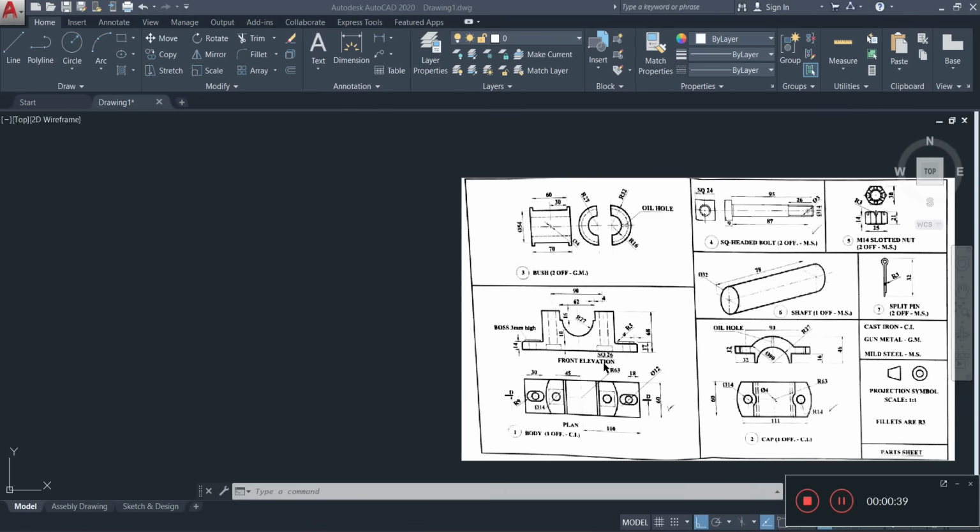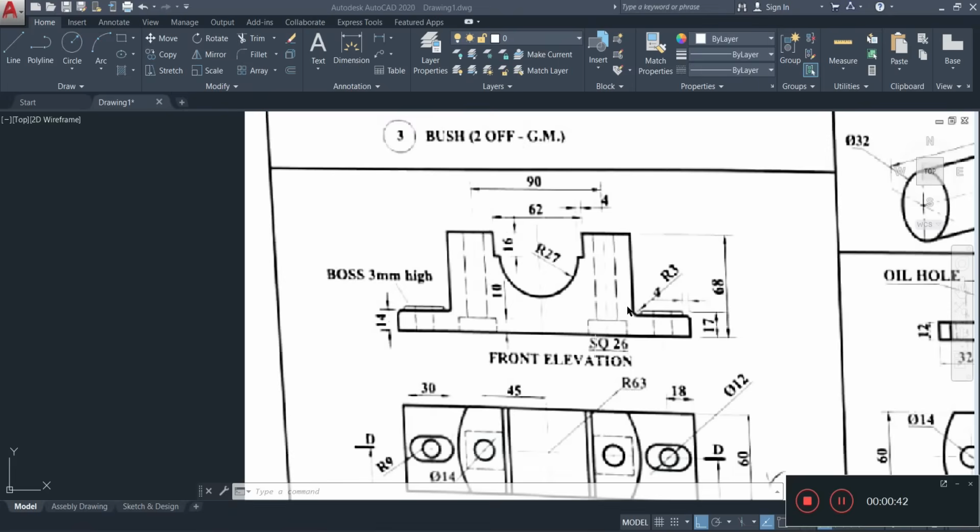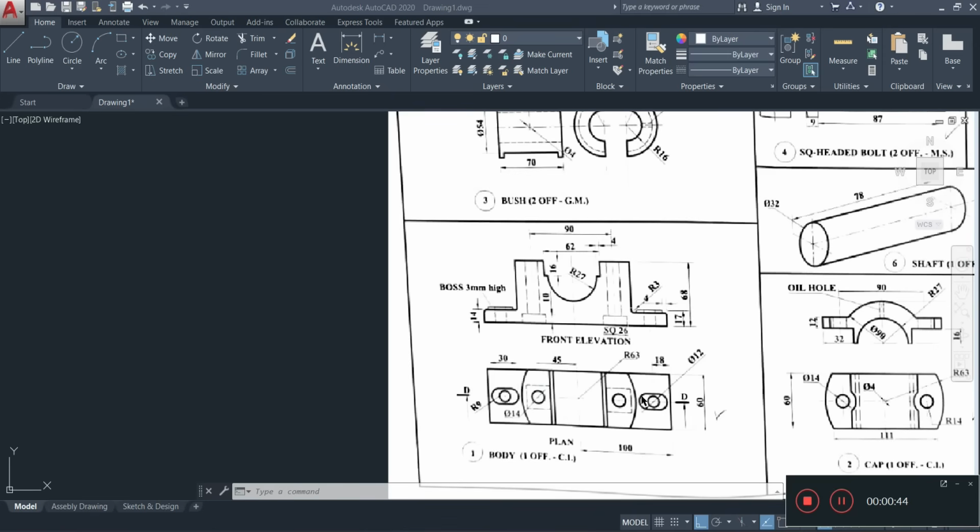Now for the section, based on where it is cutting, D-D, right across the middle here, these are representing the holes that are in the middle there. Because we're cutting through these holes, from a sectional view perspective, all these hidden detail lines that you're seeing here are going to become solid lines, outlines or object lines, if you want to call it that. That's the only thing that is going to change in relation to the elevation views.